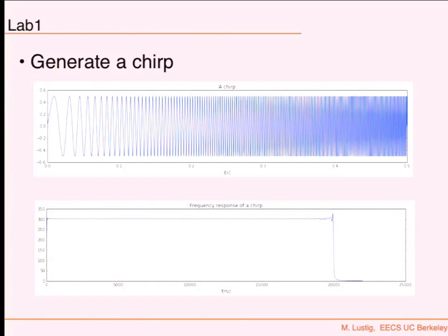If you want to generate something that has all frequencies, and you don't want to use a chirp, you use a delta function, for example, or a sinc if you want a large bandwidth. This is very different from a sinc, but still has similar characteristics. A sinc function would have constant frequencies over a certain bandwidth. This also has a constant frequency over a bandwidth, but it definitely doesn't look like a sinc.